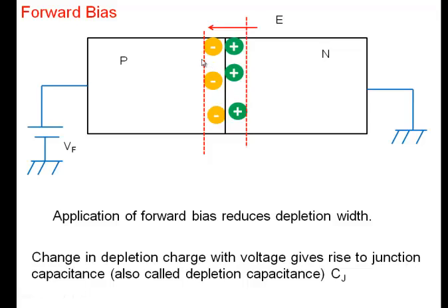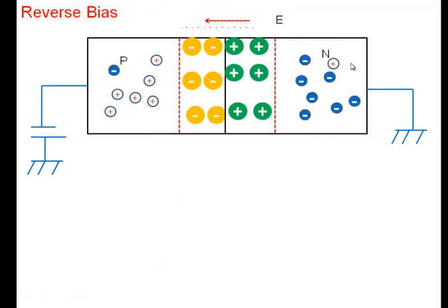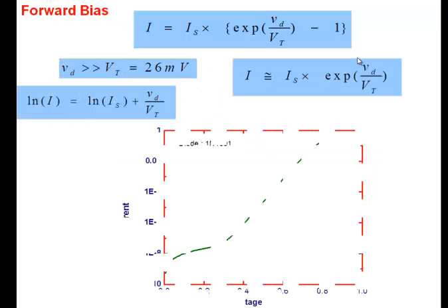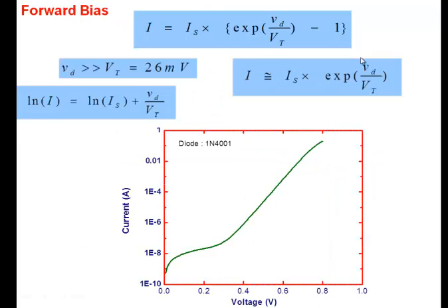Okay? So when you apply 1 volt, you don't overcome the built-in voltage. All right. So when I say that this voltage that I've applied goes all the way and appears over here, that's only true up to a certain point. Beyond a certain point, more and more of this voltage gets dropped here in the P and N region. And that's the reason why the current that I've drawn here, if you look a little closely, increasingly starts curving.